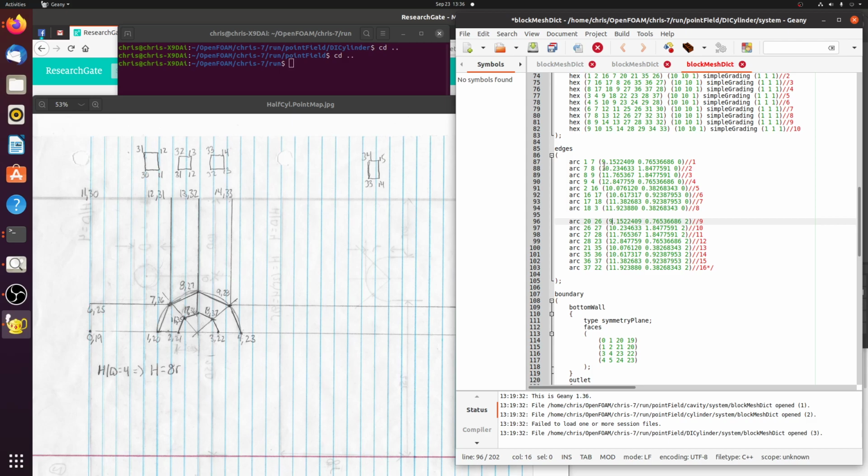When you do the arcs, you want to go out with as many decimal places as you can, because it has to be between 2 points. You're going to be trying to create a circular cylinder, so you want it as accurate as possible. So the arc, once again, is from point 1 to point 7, point 1 to point 7.